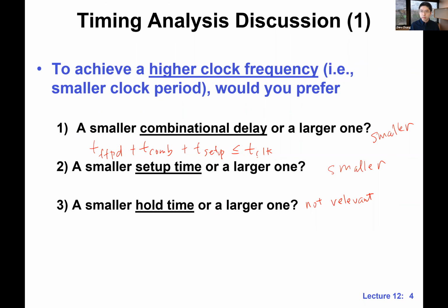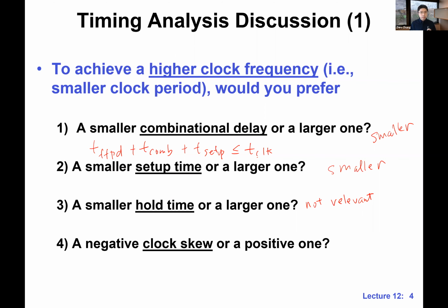There is a question. Alma's asking why not? Just look at this inequality here, Alma. We don't even have hold time over here. The clock frequency is not constrained by the hold time, and we treat this hold time violation as a separate constraint.